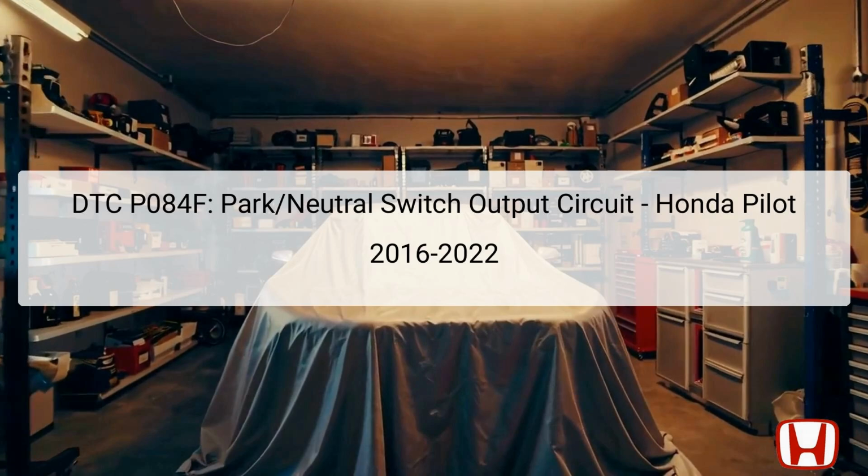DTC P084F refers to a malfunction in the park neutral switch output circuit in the Honda Pilot, model years 2016 through 2022. This code indicates that the vehicle's electrical circuit has a problem that affects the park neutral switch, which is a critical component in determining the transmission's operational state. Essentially, the park neutral switch informs the transmission control module, TCM, whether the vehicle is in park or neutral, which is crucial for starting the engine and ensuring proper functioning of the transmission.